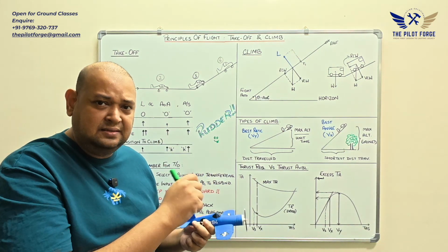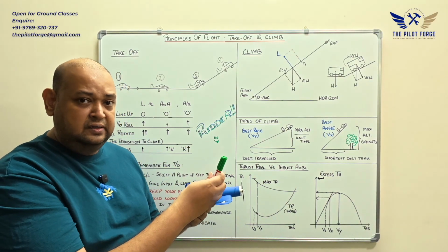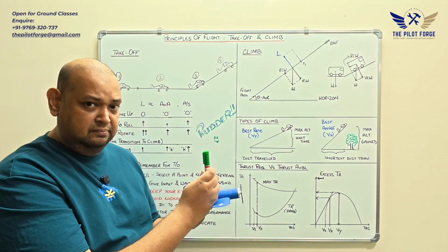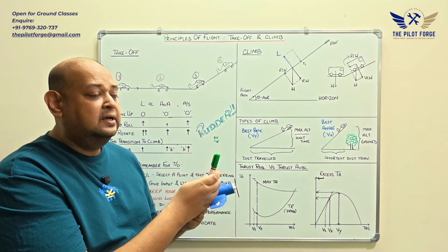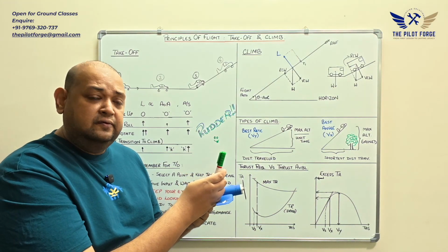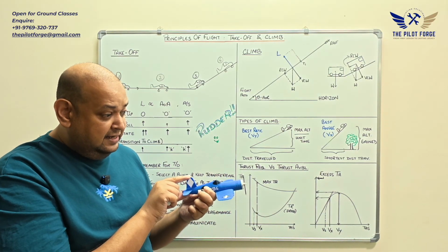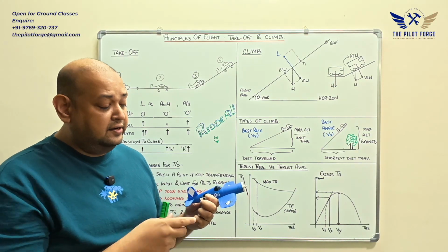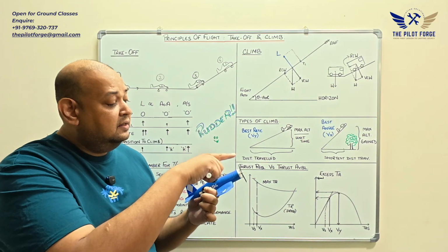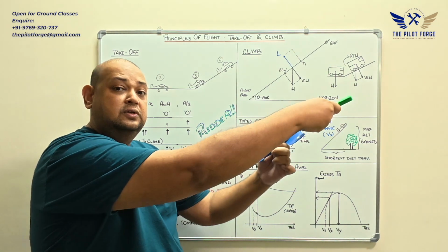You don't peel the aircraft off the runway. It's not a banana skin, okay? It's just an aircraft. You have to give it the input, which is control column back, as much as is required, usually about 2 or 3 inches. And then you wait for the aircraft to respond. It'll respond by gently raising the nose, where you will need to stop it at a particular attitude. Once the attitude is set, the excess thrust takes over and the aircraft then continues climbing.